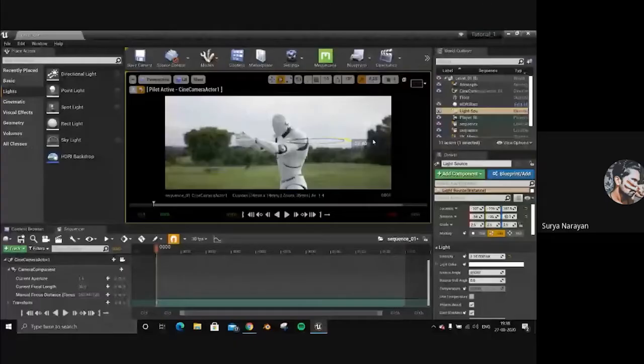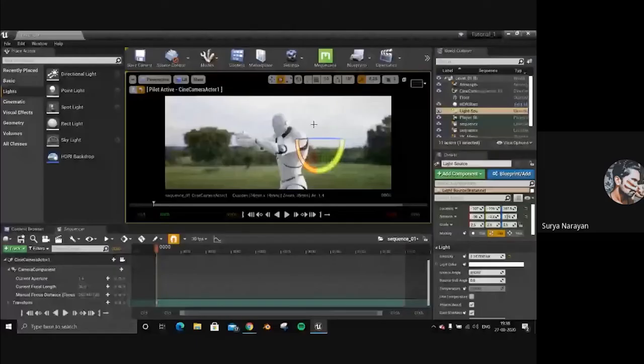There is our directional light. So we're gonna switch this to the rotation mode and rotate our light. That's gonna change the shadows and the position of our directional light. I think this is good. You can tweak these settings according to your needs. You're free to do that. And I'm going to press G on my keyboard to hide the light.